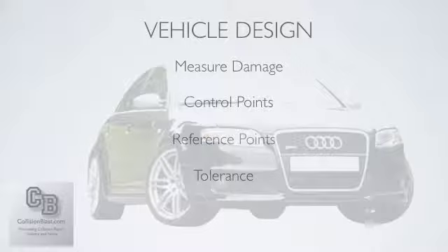And if it's off just a little bit, the body panels are not going to line up, and you're going to see uneven gaps. In the body over frame in the older vehicles, you could adjust the panels to make the gaps line up. But if you're not dead on with these newer unibodies, it's going to be very noticeable.